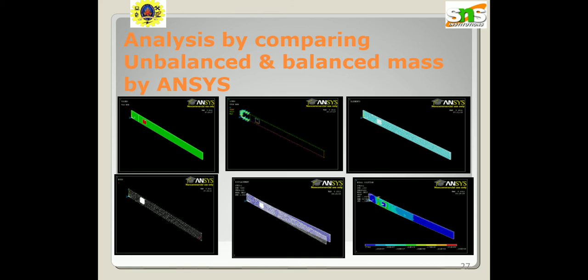And the next one is the tuned mass damper, introduced as a part of the suspension system by Renault-Nissan. In the production of car companies, tuned mass dampers are widely used in the crankshaft pulley to control torsion vibration, and more rarely the bending modes of the crankshaft. They are also used on the driveline for gear whine and elsewhere.